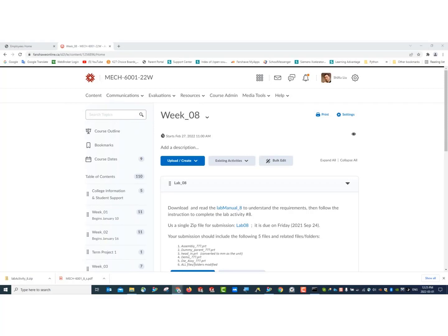You're going to practice those. Reference set is another way to organize what you're going to display. By default, you have entire part, which will display everything. The second one is model. Only the bodies will be displayed. The curves and other things such as sketches will be hidden. The empty set will display nothing. You can add, edit, or remove some of your reference sets, add some elements in the reference set, and then show different displays.